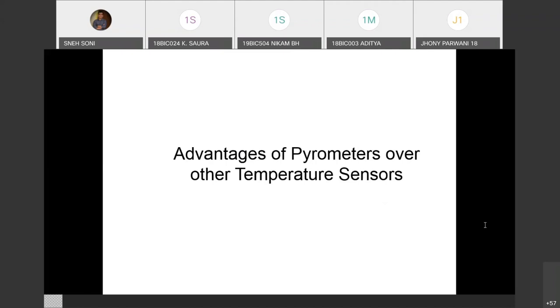So you encounter such problems when you mount a sensor. Here you have non-contact temperature measurement, so you need to adjust the lens properly, and then you can see through the eyepiece. With an optical pyrometer, for example, you can adjust and get the temperature without even coming in contact with the physical body. Right? So this is an overview.